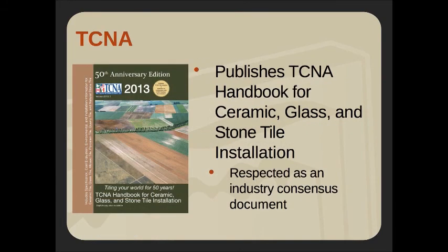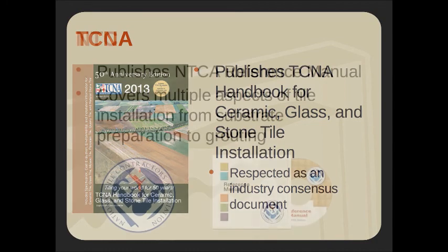TCNA, it's got a fantastic handbook for ceramic, glass, and stone tile installation. I refer to this one often as well. It's respected as an industry consensus document. It's got very specific detailing. If you're not aware of that manual, it's something you should have. So it talks about some of the nuances in dealing with stone tile as opposed to ceramic. And then if I don't know what the setting method is I want to use for a shower wall, for example, it has that detailed for us, and there's your detail to utilize in your drawings and specifications.